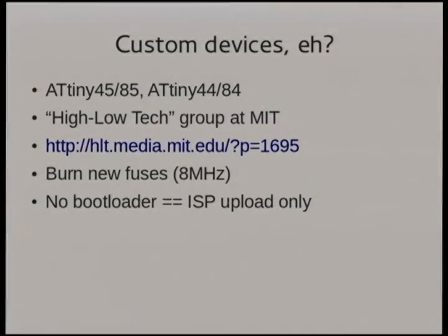So the other thing you can do if you're looking at custom devices is the high-low tech group at MIT has actually gone and ported those Arduino libraries, or at least the more critical and more used parts of them, to smaller devices that are in the same sort of processor family as the ATmega328 chip that the Arduinos currently come with. And out of those, I happen to use the ATtiny85 quite a bit. It's really convenient because it's only an 8-pin package. So it's really, really small, but you can still solder it yourself.